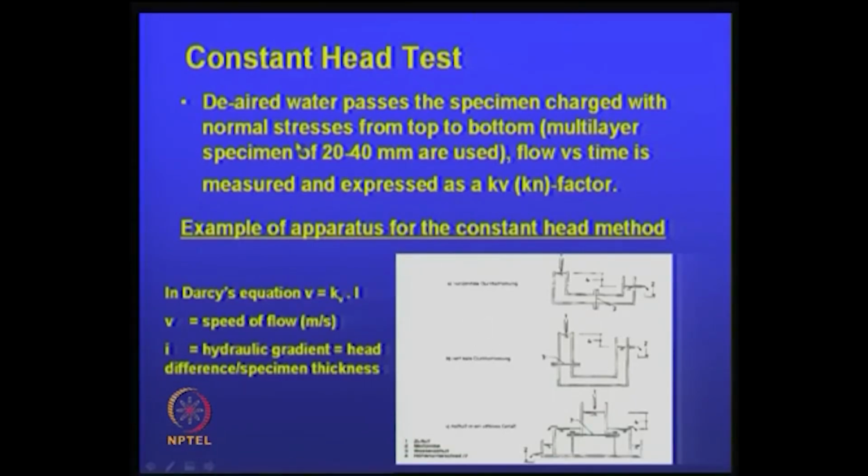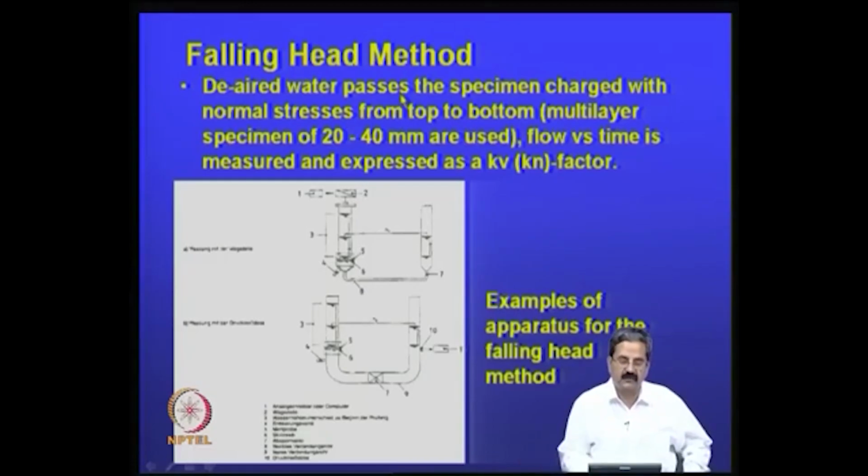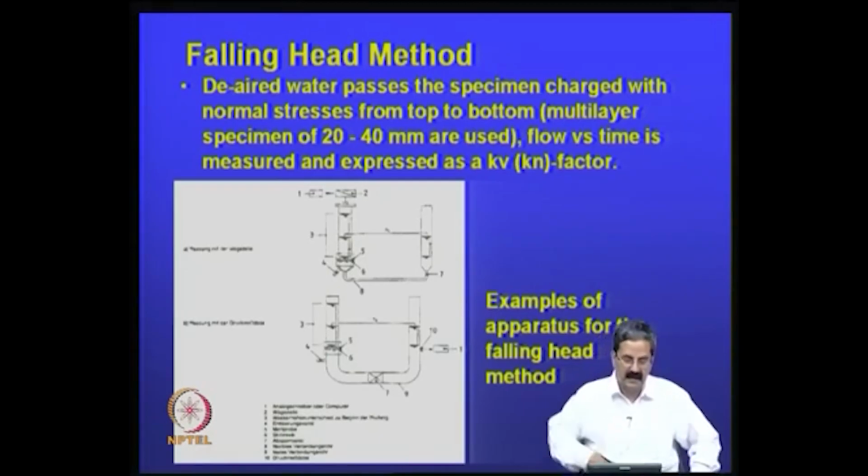So, it can be measured, flow versus time, and using Darcy's law one can calculate the permeability. Then falling head, again a similar thing was done here, again with deaired water. In fact, in permeability testing we should use deaired water, because you do not want air in the water. The deaired water passes through the specimen charged with normal stresses from top to bottom, and multi-layer specimens can be used. Flow versus time is measured, and you can calculate the permeability. There are some specific equations there.